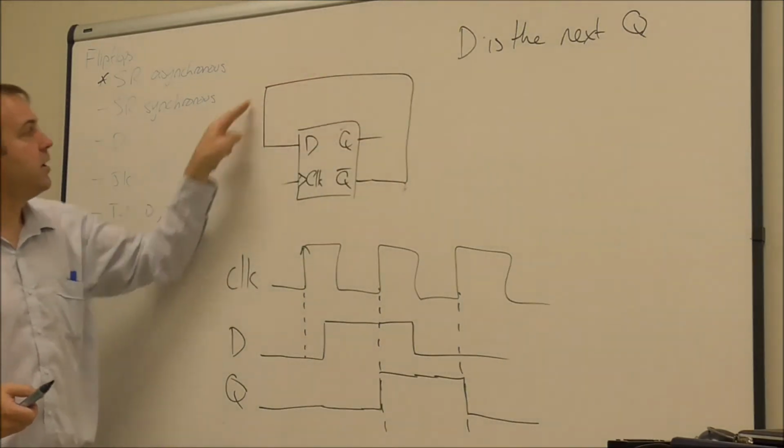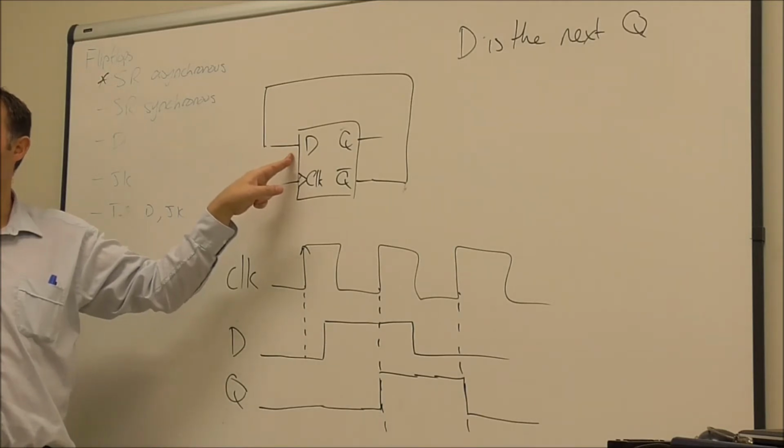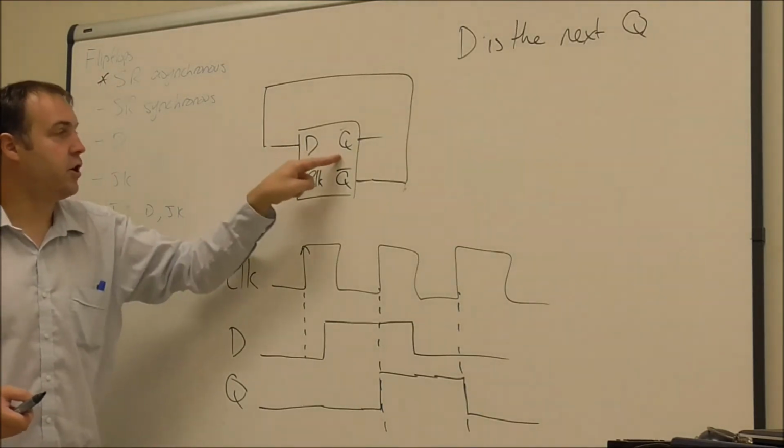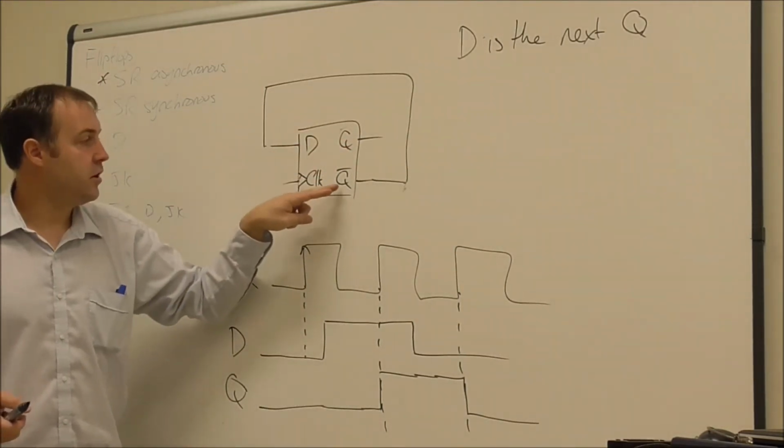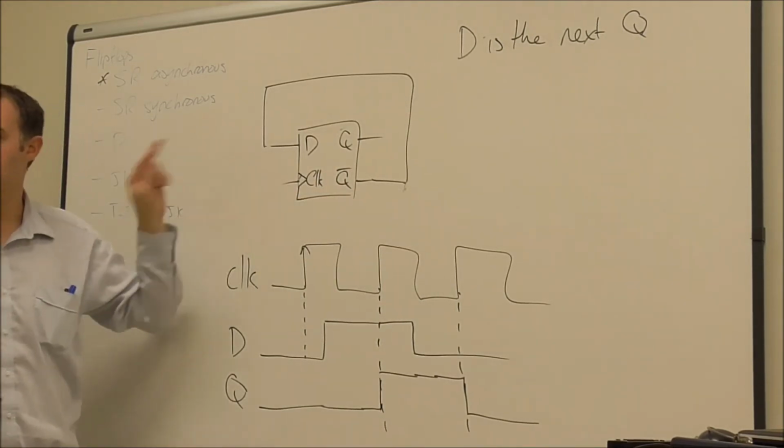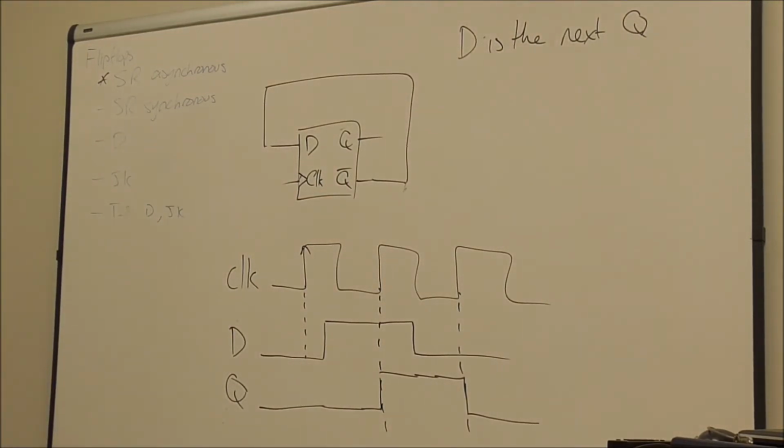So now we're back to 0. So now D is low. Next clock pulse, Q goes back to low again. Q bar goes high, so D goes high. And so every clock pulse, it toggles this circuit. Okay? And so I've kind of shown how that's done here.